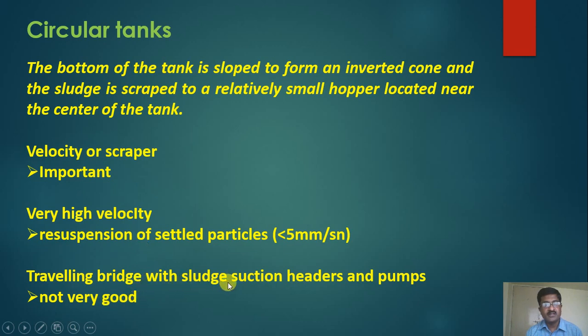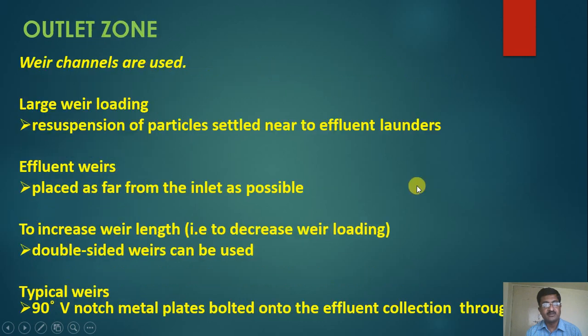Traveling bridge and the sludge suction headers and pumps. If the synchronization between the traveling bridge and the pumps is not properly maintained, there will be problems in this process. So all these things should be synchronized properly, so that proper sedimentation takes place.